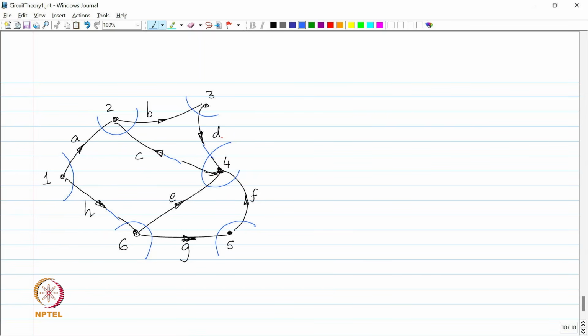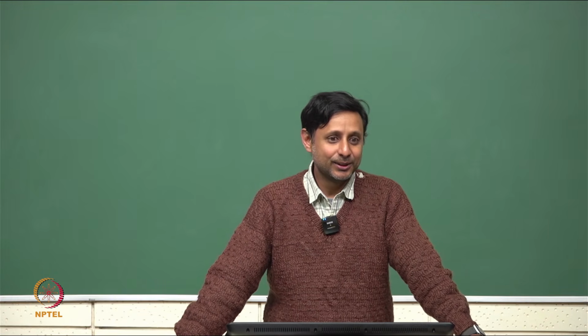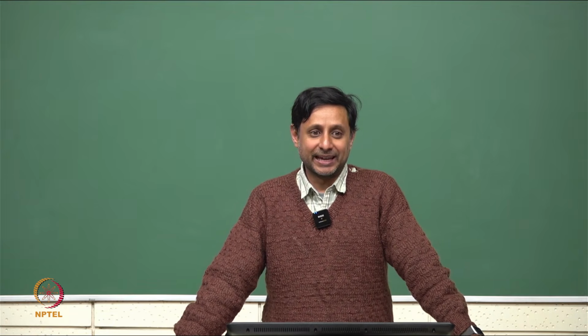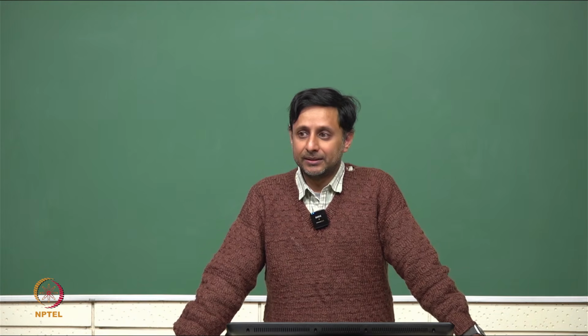Are they going to be linearly independent or dependent? They can be independent, but they might not be independent also. No, wrong. They are always linearly dependent. They are guaranteed to not be independent. Why? No KVL, I am doing only KCL. They will give n equations, but I have only n minus 1.